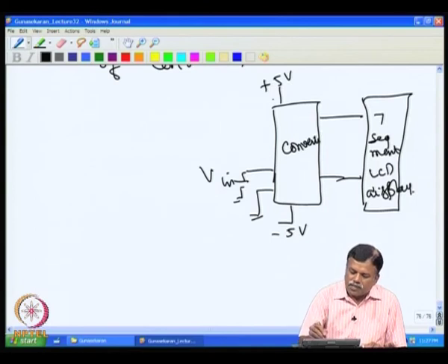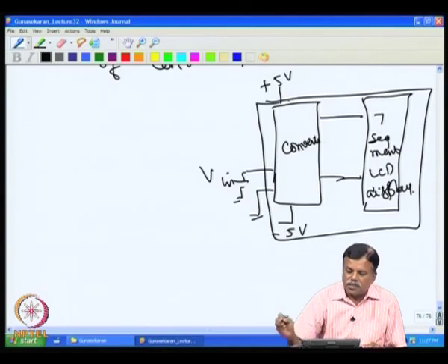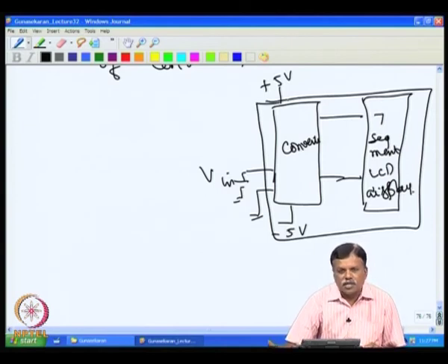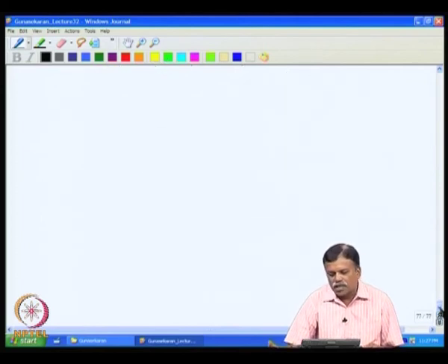So, this is available as an integrated module which one can use for displaying values, converting the analog value into a digital value. This can also be used in other applications wherein we want to digitize, but the noise should not enter the instrument. The only thing is it will be slow. For example, we can use a microcontroller and do this kind of conversion.